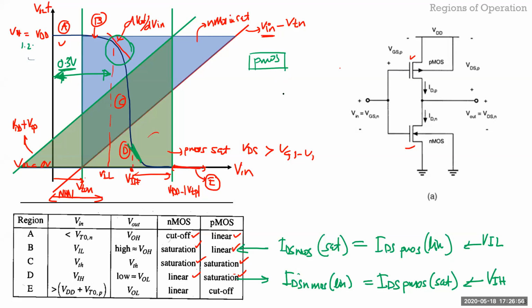If we increase the strength of PMOS, it will hold for more time, for more value. Exactly. So what you're trying to do is shift the curve to the right. The PMOS is going to fight the NMOS for a longer time before the NMOS switches on. That's why you want to make the PMOS size larger. Typically in a simulation, when you're designing, you get to a certain VIL and say, I want to increase this, so you just increase this size a little bit and get your number, because the calculation you're doing is very approximate.